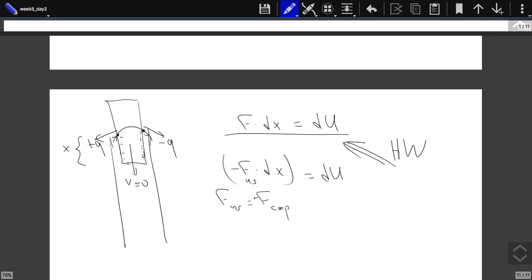And if you just evaluate this U as a function of x, x being this distance, F is just dU by dx. So you can actually calculate this force. And in this derivation, by the way, you don't need to take into account the fringing effects. It's enough that you assume that the electric field lines are horizontal to calculate this U. Still, the force that you calculate will be the correct one.